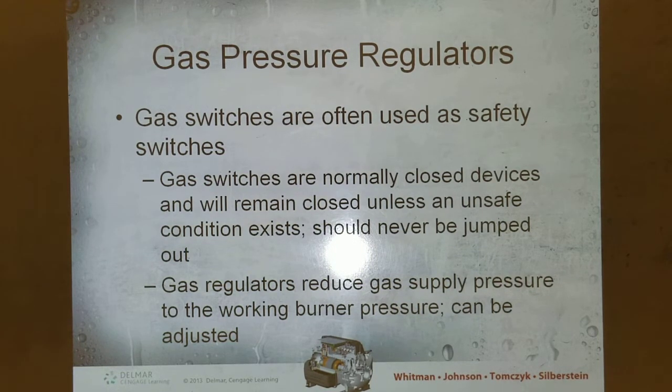So if, by chance, you're working in heating, and the system is acting funny, and you can't quite figure it out, and the burners aren't coming on the way they should, if you feel that system is unsafe, your job is to turn it off, cap it, and red tag it. If you're not sure, red tag it, cap the line, and walk away from it.